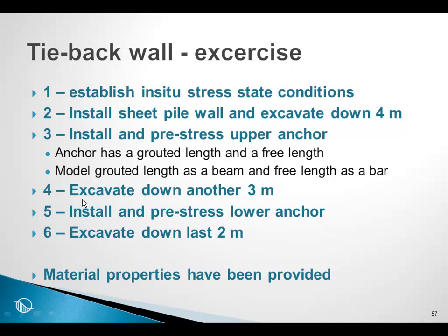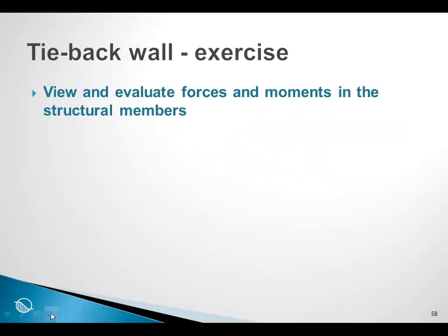Once that has been done, we'll go to another analysis to excavate down another 3 meters, then install and pre-stress the lower anchor, and then excavate down the last 2 meters. In the essence of time here, we have provided the material properties. However, you will have to define the boundary conditions that simulate the excavation and removal of the material. In the end, we want to view and evaluate the forces and moments in the structural member.